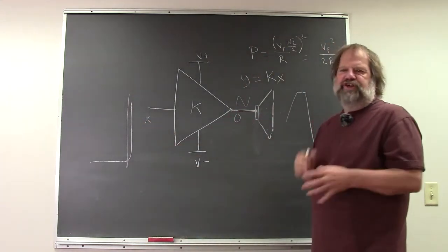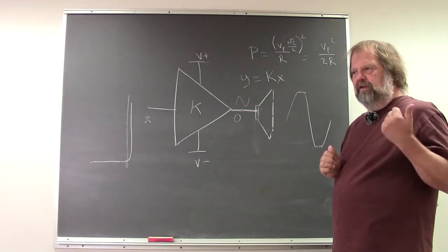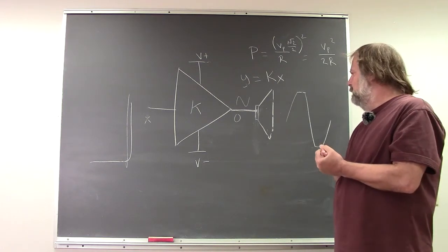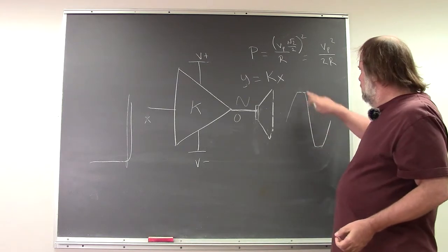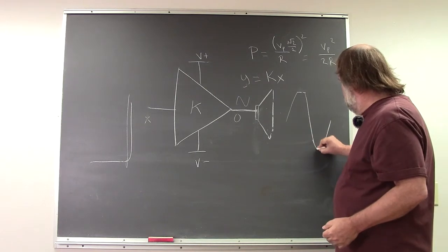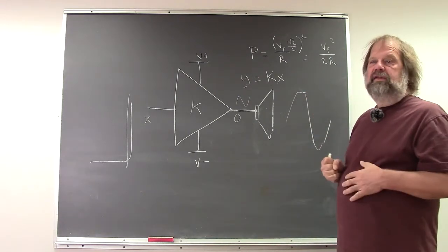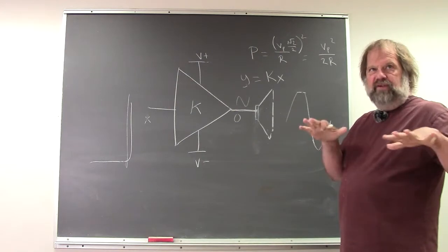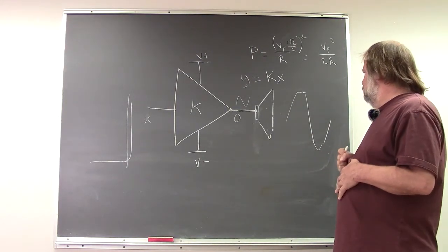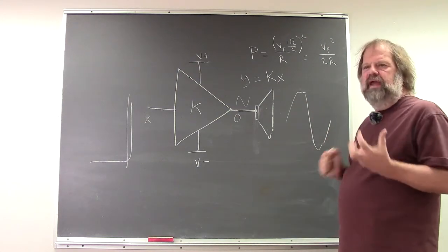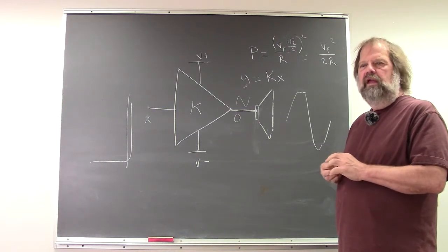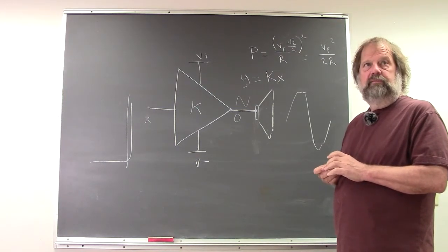And so we're not talking about subtle distortions of a little bit. We're talking about horrendous distortion at this point. When you have clipping, if it's symmetrical like this, it creates odd harmonics. If it's unsymmetrical, in other words, one side clipped first, it creates even harmonics. Neither one is going to sound pleasant. I'm not talking about very subtle distortion now. We're talking about hard clipping. And so the first thing to take from this discussion is any amplifier, no matter how good you think it might be, is a bad amplifier when it's clipping.